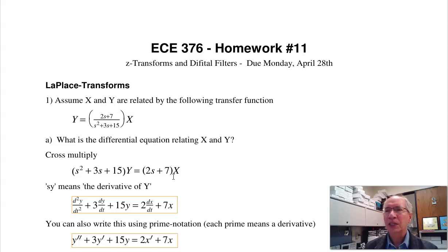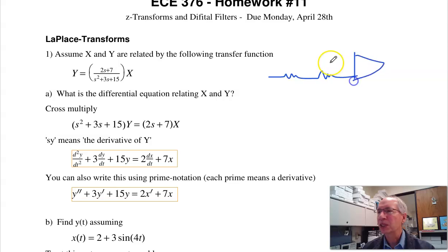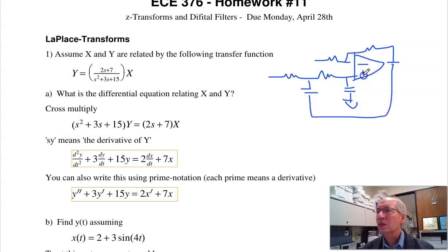In hardware, if I build a filter, I'm usually using Laplace transforms. Again, if I have a low-pass filter, for example, here's one circuit for a second-order low-pass filter with complex poles, something you cover in electronics. I have an op-amp circuit with two capacitors. This guy right here would let you implement complex poles with an op-amp circuit.